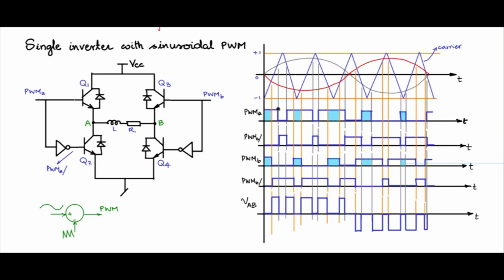That is, we turn off this a bit earlier, and we turn on Q2 a bit later, so that you can fix a period of time called the dead time period, when both Q1 and Q2 are off, that you have ensured Q1 is off and Q2 is still not turned on. So this is a problem that we need to solve.